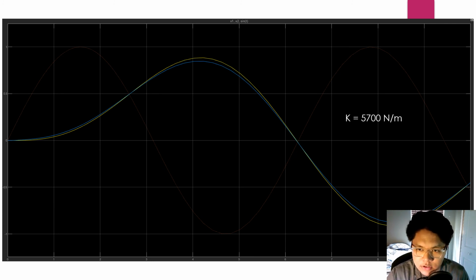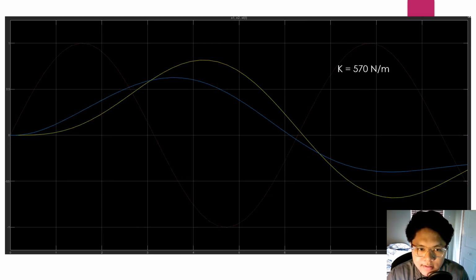function, and changing it to 1/10 of this, we can see that the differences between x1 and x2 are much more dramatic and less sensitive to the road function. As you can see, there is a bit of delay here as the road goes down, between the road going down and the change of the distances x1 and x2 going down around here.